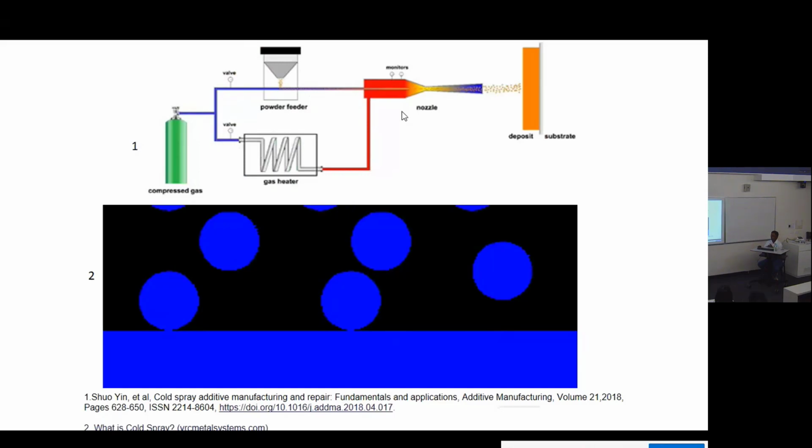In order for this bonding to happen, what normally happens is, in general, metals, when left to themselves, will form an oxide layer on the top. Except for gold and platinum and palladium, all of the other metals will not be found in the native state, they'll normally be found in a combined state. And in the same way, when the powder hits against the substrate, it removes the oxide layer, and then two clean metals come into contact with each other and they form a bond. So thermodynamically, two clean metals, when brought into very close contact, cannot stay that way. They'll form a bond, a metallurgical bond.